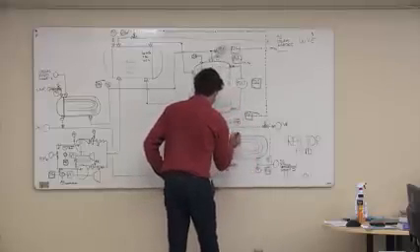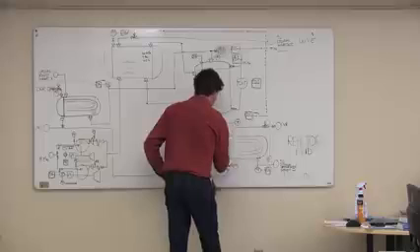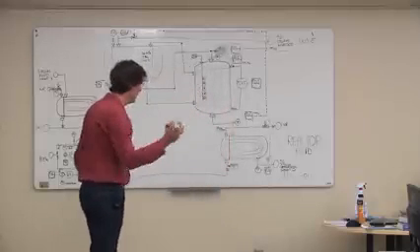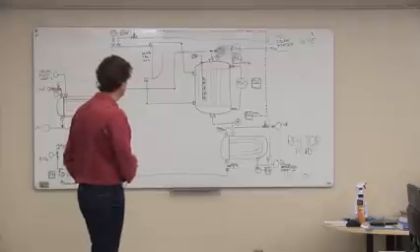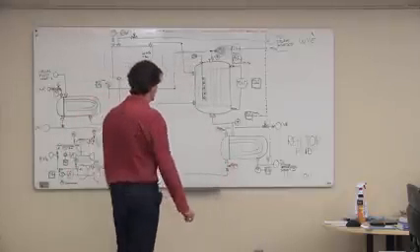That's kind of handy to have, and we'll just put that on here as well. If you had to, you could just do it with separate gauges. PI, TI, like that. That gives us inlet pressure and inlet temperature, just in case you want to walk out to the field and look at what the differential pressure of the heat exchanger is on the water side.